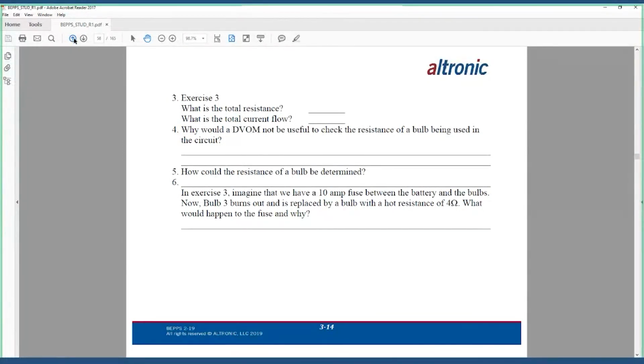Okay, so if I go E over I equals R, we want to find out our I, so we're going to take E and divide by R. Does that sound right? That's how I remember Ohm's law: E over I equals R, because if I can draw it out, then I can see the math formula in my head. So E, our voltage, is 9, and we divide by R, resistance, 1.9, to find out our amperage.